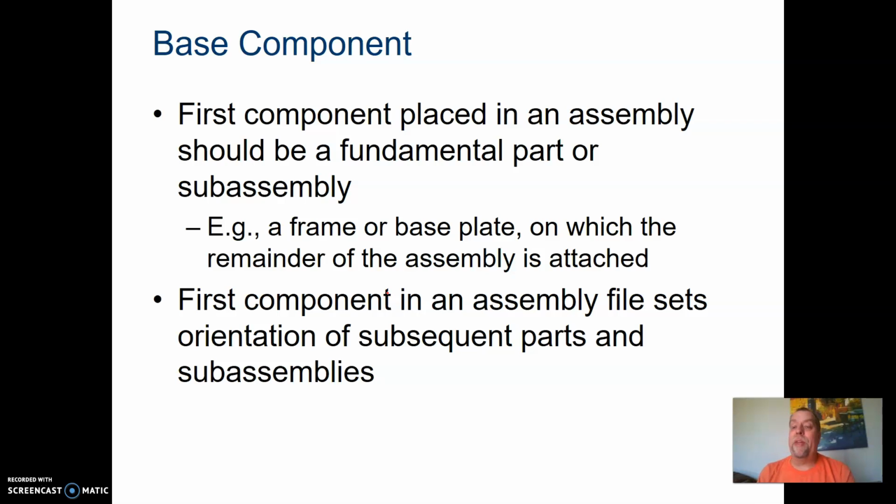Your base component, that first component that you bring into an assembly, should be the main fundamental part of it, or possibly a subassembly, a frame, a base plate, something like that. The first component in the assembly file sets orientation. So if I want to set this as my front view here, I want to set it up like that.